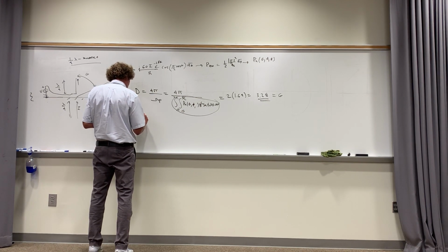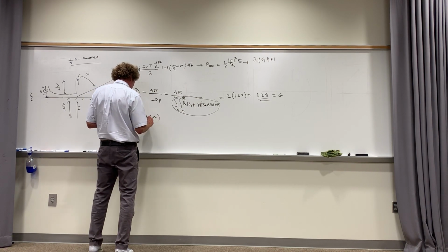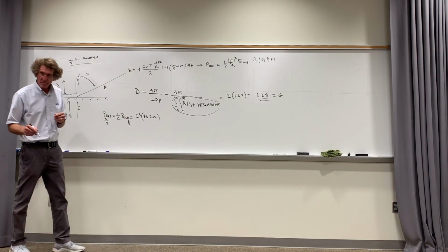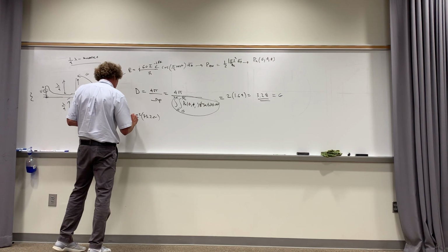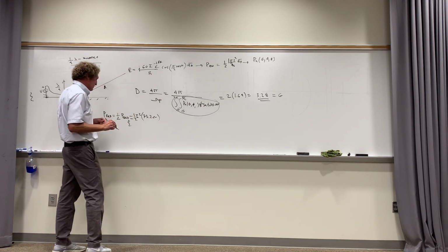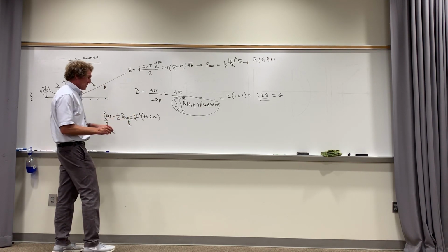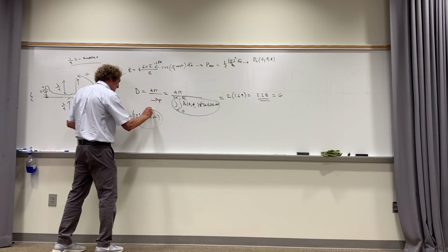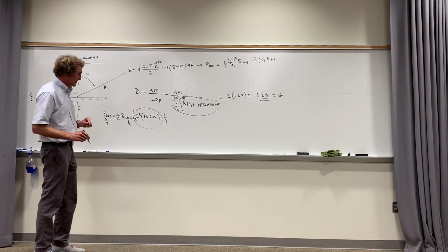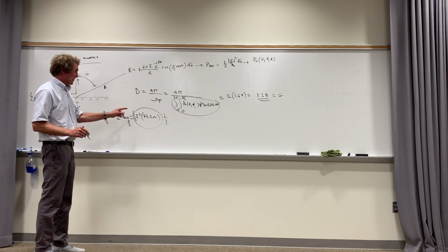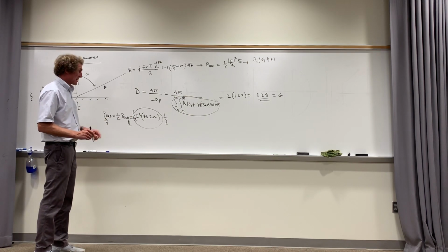And then it was times 73.2 ohms for the radiation resistance. Do y'all remember that, class? And it was actually times 1/2 this, by the way. That was equal to P rad. Well, if you take this quantity and divide it by 2, then you get the P rad for the quarter wave dipole. So it'd be 1/4 I squared times that.